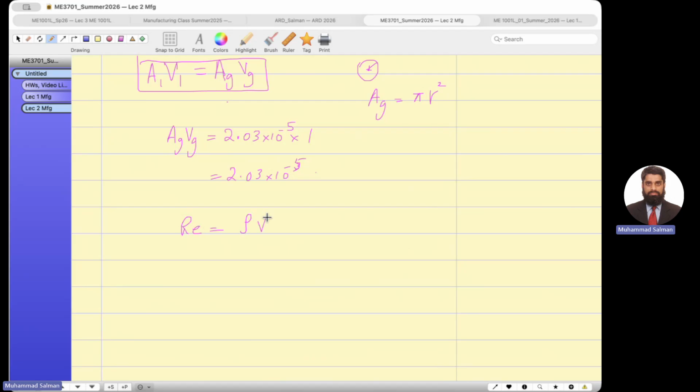Reynolds number rho VG dg divided by eta, and make it 20,000. 20,000 is still okay in casting. And can you solve for this value, VG dg combined? That will give you another equation, so you can plug it in over there.